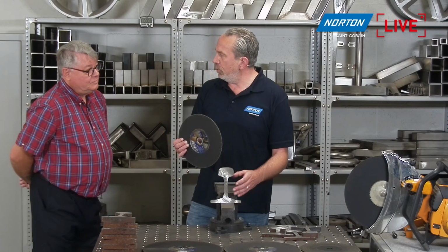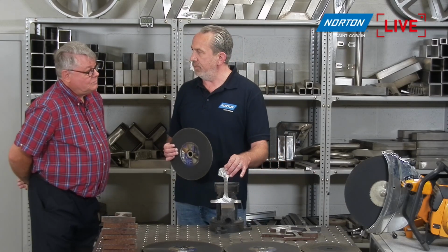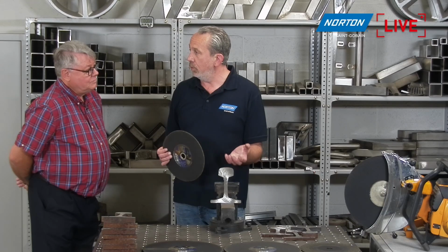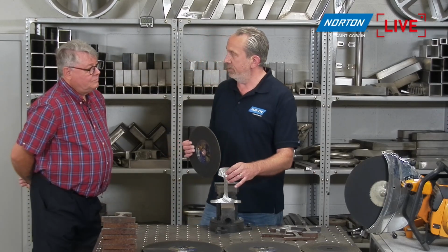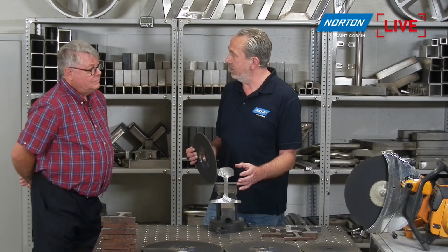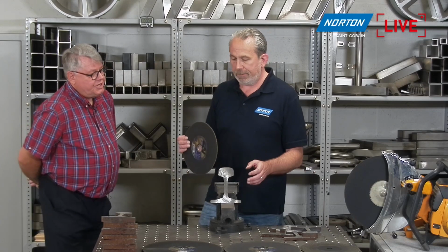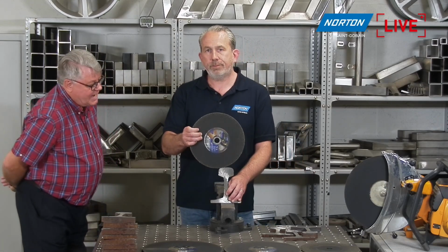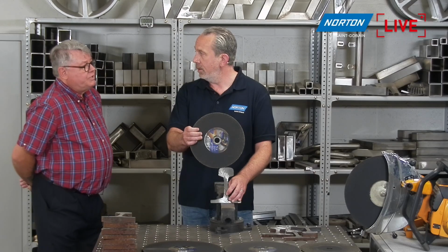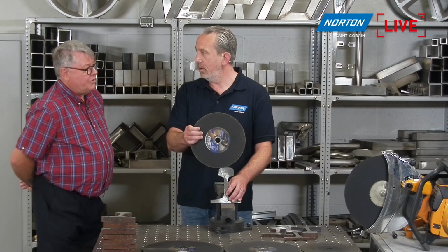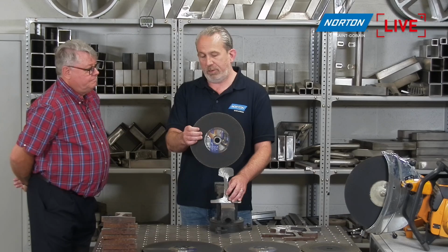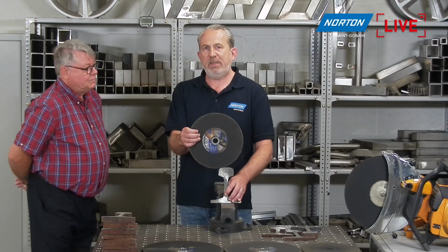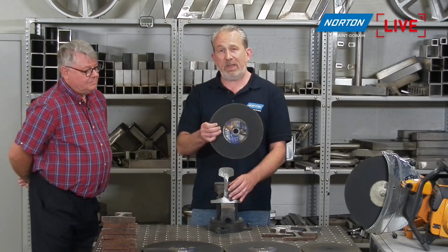When we put too much heat into this material and we start to blue it, that's detrimental to the rail. It changes the metallic structure and makes it far more difficult to do the finishing process, which is welding the two rail ends together. So it's a real big no-no. If you see bluing, it's a problem. We want to avoid that, and that's down to technique.